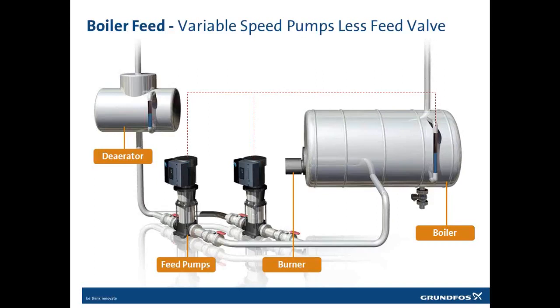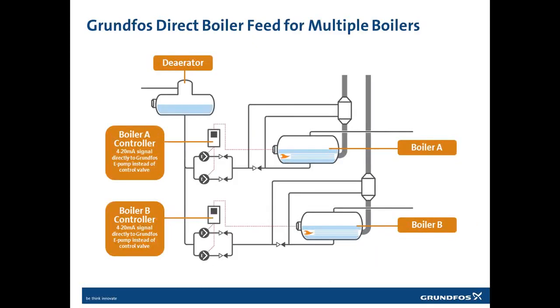Another question that might have to do with the next slide, something about non-return valves. Shall they be installed? The question was, shall parallel pumps be separated by check valves or non-return valves? Yes, they must always be.